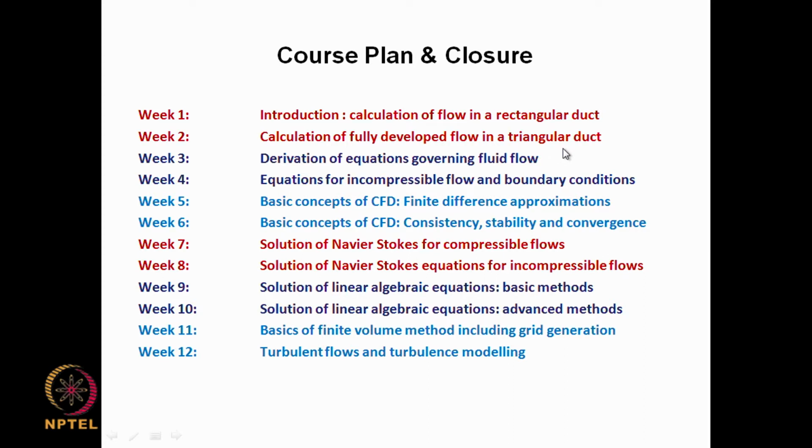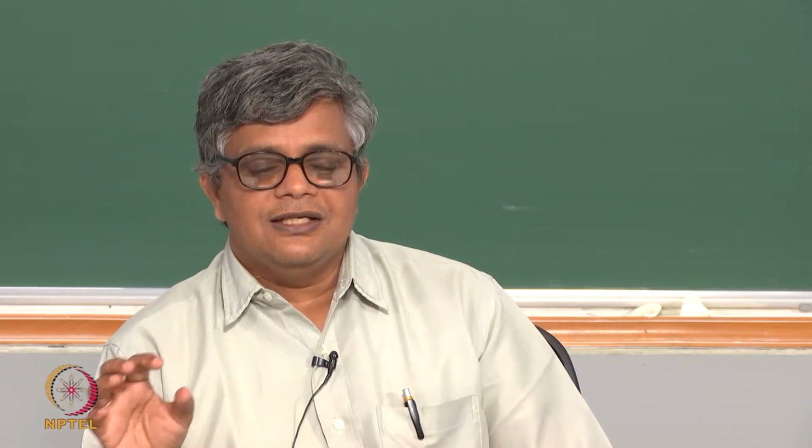We introduced the basic concept of a CFD solution: how you take a partial differential equation, substitute some approximations, convert it into a set of equations, and solve them together to get a solution. We also introduced the Gauss-Seidel method there to show that we need some specialized method for the solution of these linear algebraic equations.